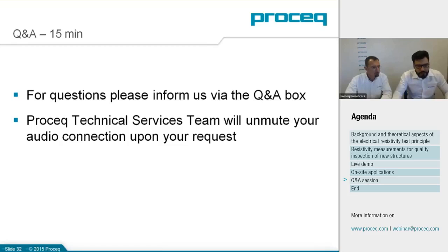Is the concrete cover affected by the resistivity? So is concrete cover affected by the resistivity, or is resistivity affected by the concrete cover? No, it is not. The only factor related to cover is that you might have some noise from the rebars, but you have to avoid those. Okay. Is it also important to take into account the content of soluble salt as well as the pH?